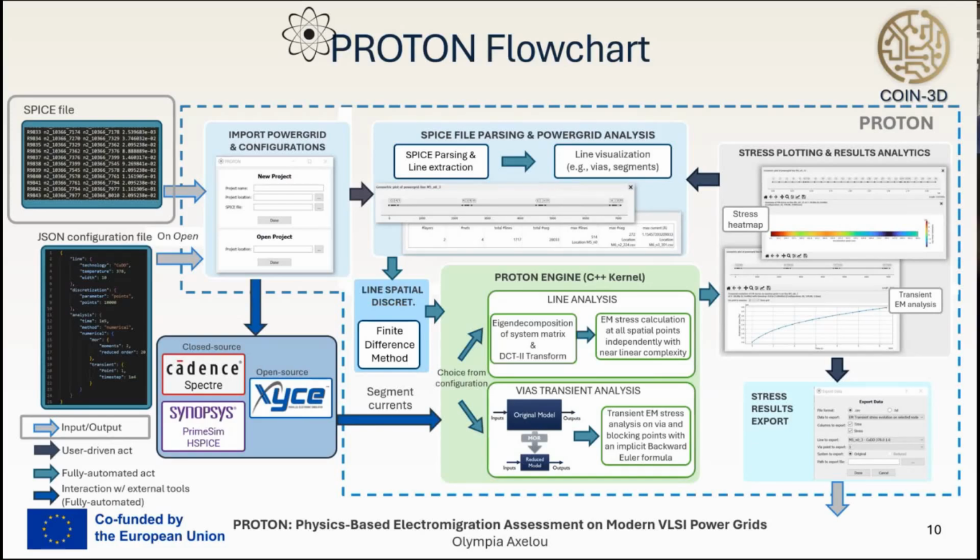This is actually guaranteed by the use of the widely accepted SPICE format for power grid design for the parasitics. Also, we are always in sync with the present industrial design methodologies and commercial EDA tools, as we integrate in the flow of our tool external circuit simulators like HSPICE by Synopsys and Spectre by Cadence.